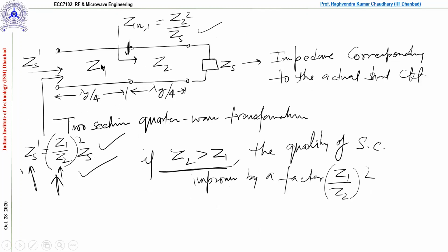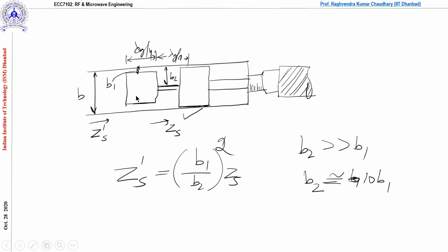This circuit critically relies on this. Here we included another pad connected with this plunger, and there is a gap, and this gap is controlling these impedances. If you manage this gap and this gap with this ratio, you can improve the overall impedance by 1 by 100. In this way you can drastically reduce the impedance, and hence realize the perfect short circuit.